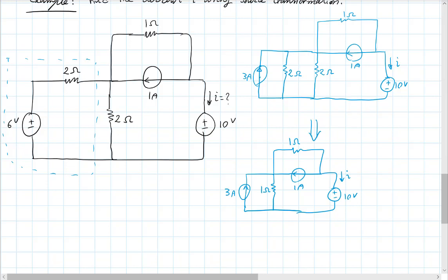Now, what's another simplification I can do, or another source transformation? Now I have essentially a Norton circuit on the left-hand side, and another Norton circuit on top here. So I will now put the Thévenin equivalent of these 2. That will give me a voltage source in series with a resistor, another voltage source in series with a resistor, and I have a voltage source. So I'll end up with just 1 loop going around. And that's what I'm hoping to get.